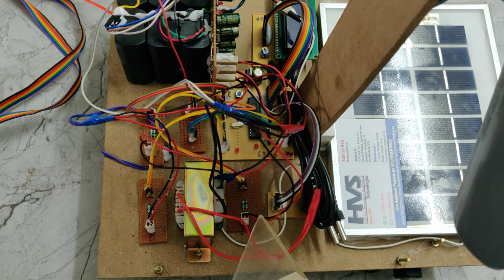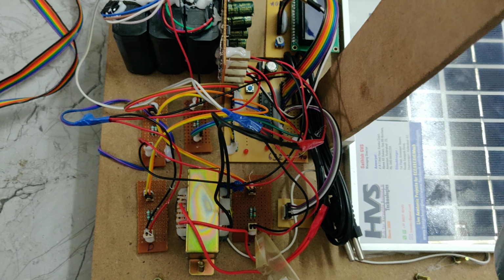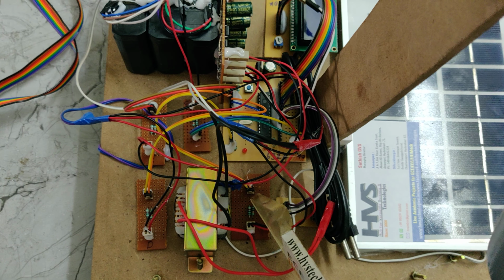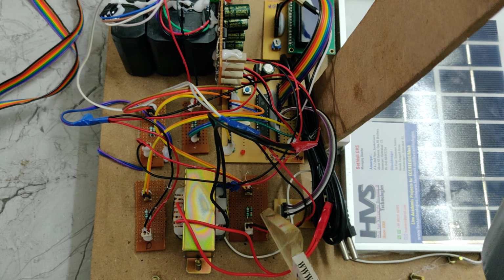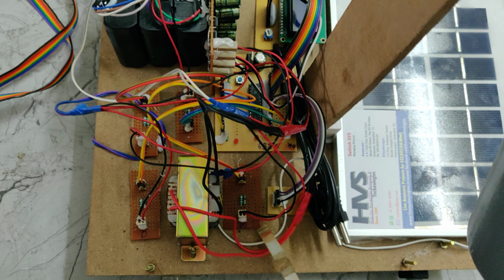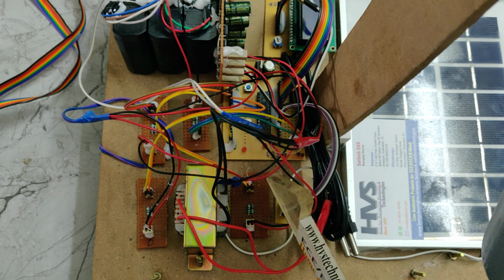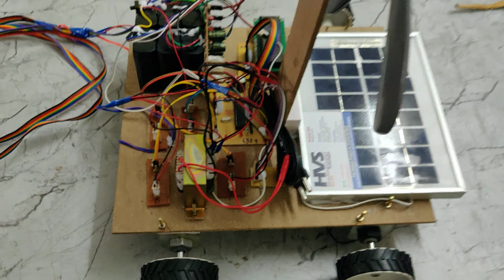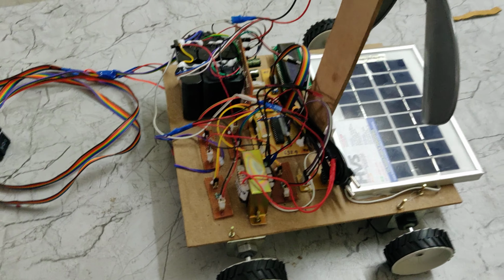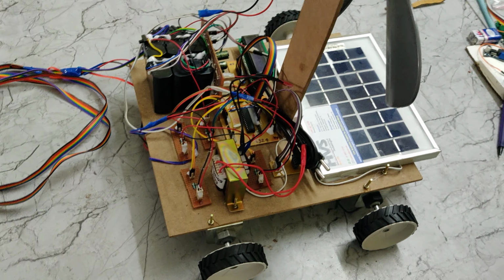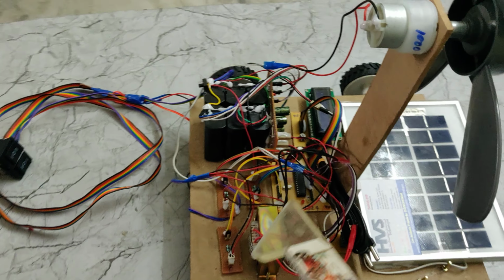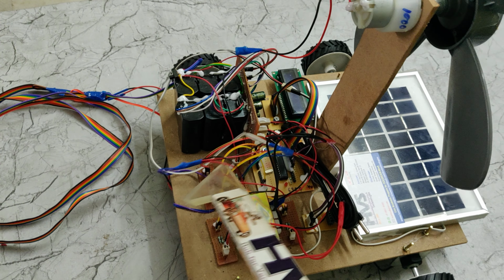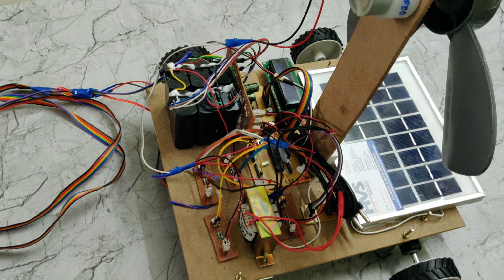So now we are providing 12 volts input to this potential divider circuit, and the output from this potential divider is a 10:1 ratio. Means if you provide 12 volts, the output from this voltage sensor is 1.2 volts. But inside the microcontroller, we have written the logic to multiply that with 10, as we are using the 10:1 potential divider circuitry. So that's why it has a 10:1 ratio, for a total of 4 voltage sensors.